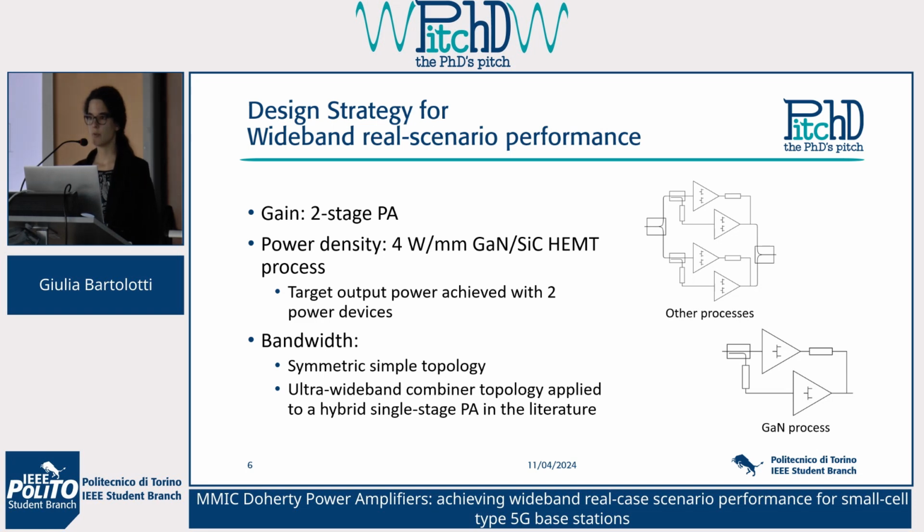How did we achieve that? To achieve the gain, we introduced two stages. So we introduced one driver for each power amplifier. In order to achieve the power, we selected the gallium nitride technology, and you can see on the bottom right how the resulting topology is much simpler compared to other ones. This simplicity also helped us to achieve a wideband design.